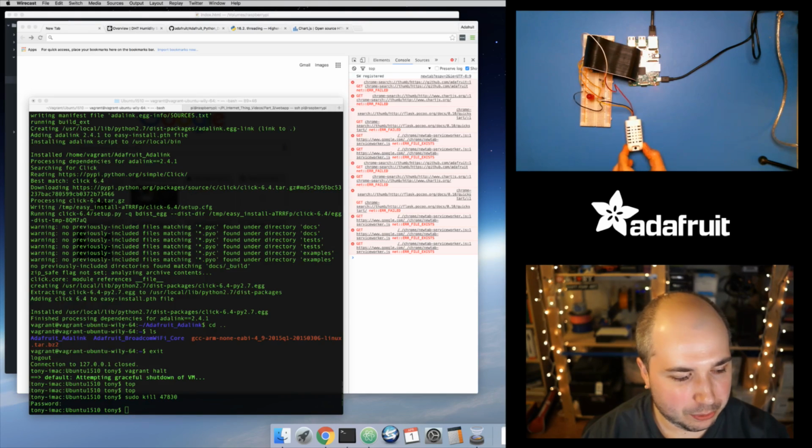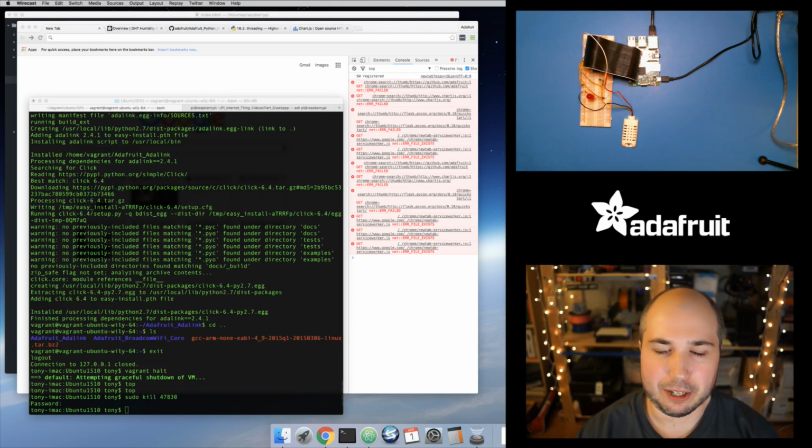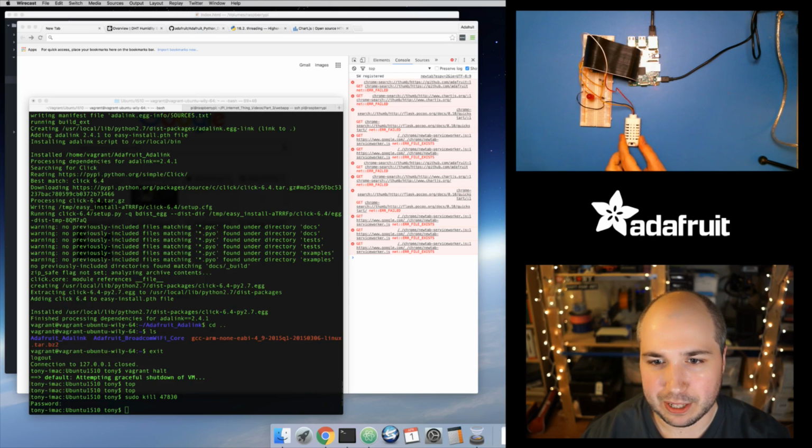And this one is kind of nice. Normally these little sensors you have to wire up and add a little resistor to, but this one's all in one. It just has some wires connected to it, and you can wire it directly to the Raspberry Pi. And I have a little Python library that you can use with the Raspberry Pi to read this sensor, because the way to read it is almost like NeoPixels, where they have a very certain signal with strict timing constraints. And so the Linux kernel is actually not that good at reading that kind of quick signal, so you have to do a few fancy things to make it work. But it's not too bad. It's pretty easy to get that sensor value.